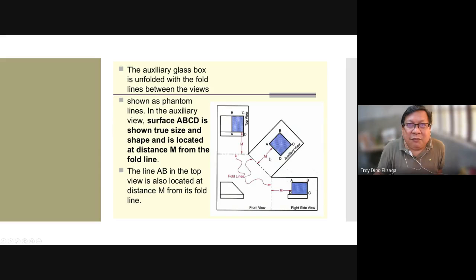Okay, that's the principle. So we mentioned earlier that we cannot have a drawing where the top view is near the front view, but the right side is very far away. Their distances from the imaginary barrier, or boundary, between two planes should be equal.